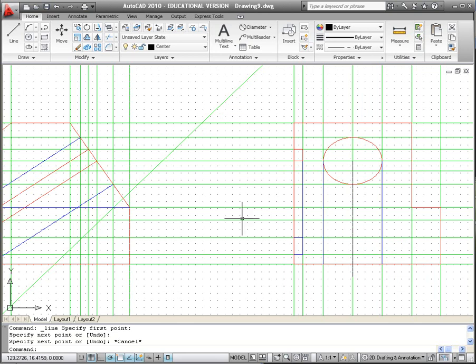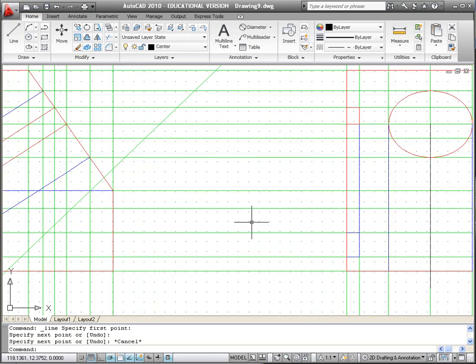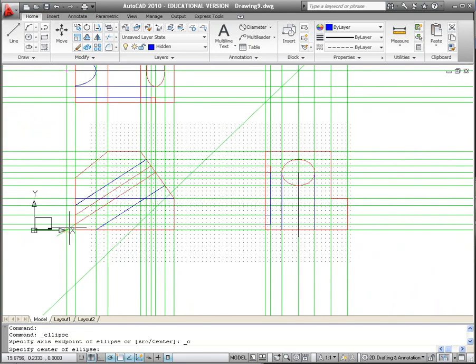The last thing for us to do is the ellipse on the bottom. If you notice where this drilling would break out through the back surface, the center is here, the sides here, and then the upper edge is there. The last hidden line to put in is this one right here. So we'll go up and select the line command, go from here over to there, and then put our line in. And that's that back edge. And we've got one more visible line that we forgot. So we'll grab it, bring it across from here.